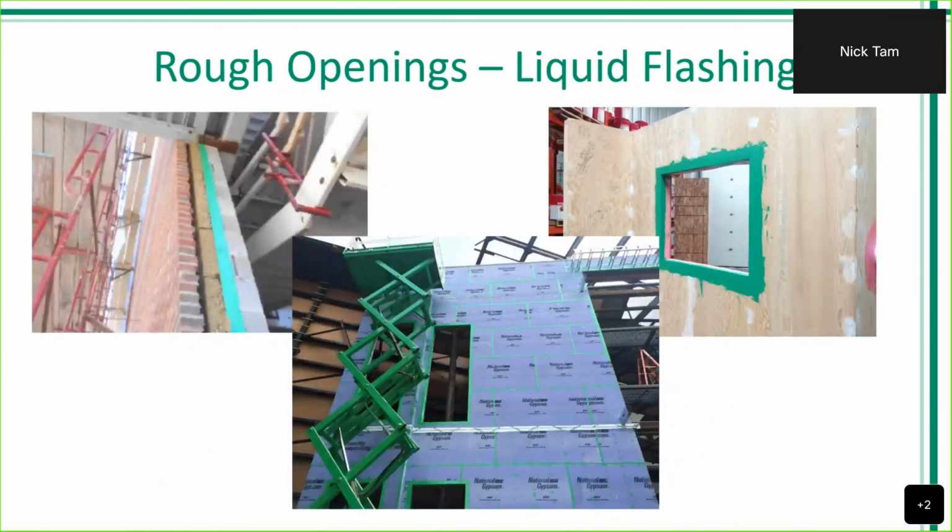But we also have liquid flashing options. Really a good option if you want to eliminate the amount of accessories needed, especially when you think about primers that had to be used to adhere the peel and stick and all the termination sealants that they use to treat the edges. These are a good option as they provide pretty good simple sequencing, especially when you think about using the same product for the sheathing joints as well.